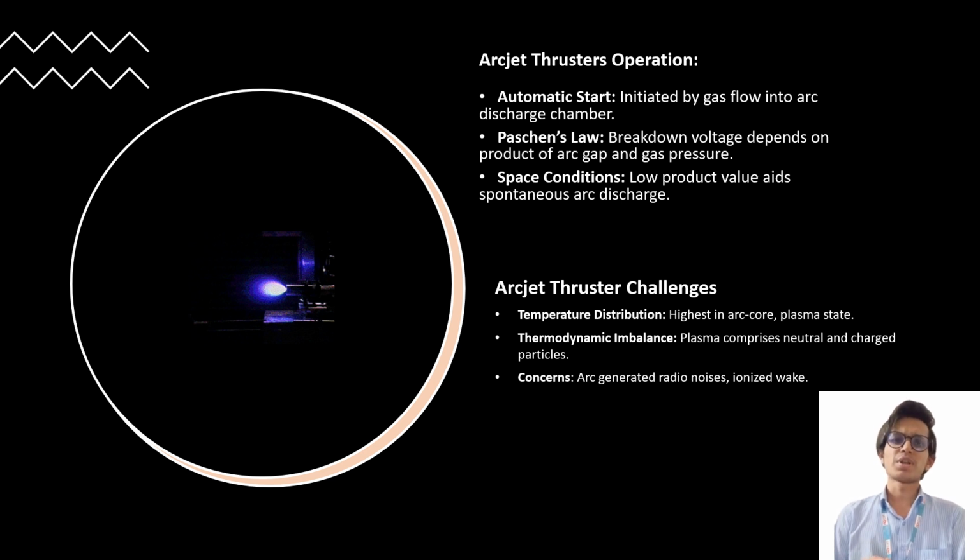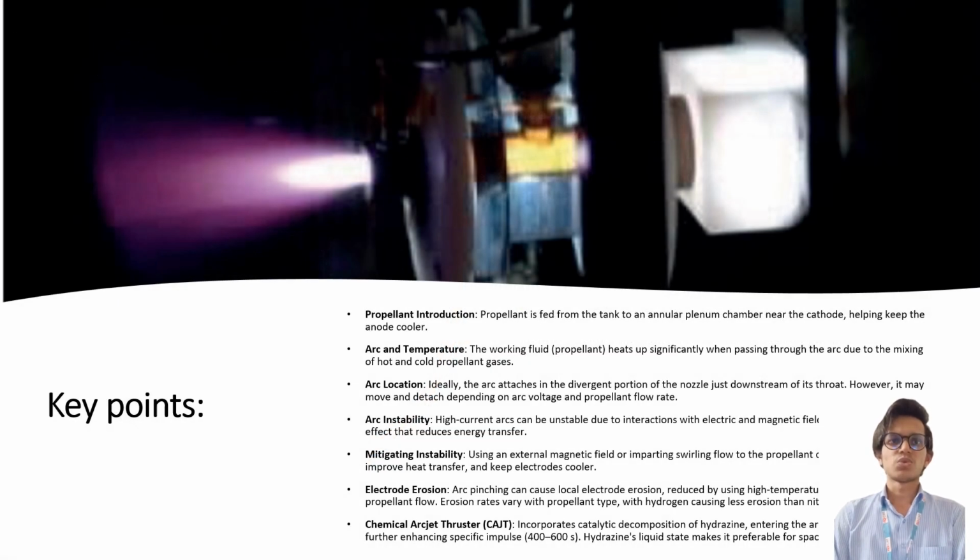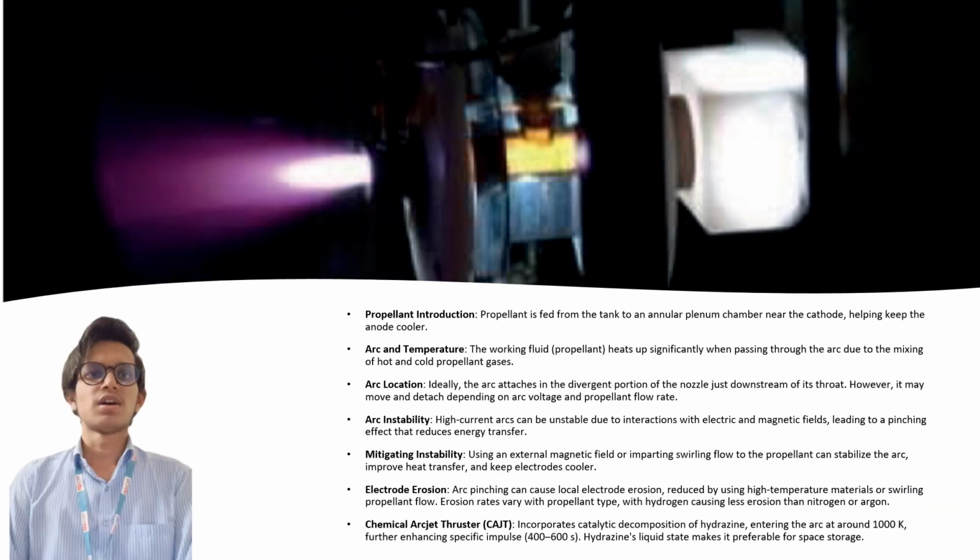Challenges include temperature distribution, thermodynamic imbalance, arc generated radio noises, and ionized wake. However, these challenges are met with innovative solutions to ensure the stable and efficient operation. So, key points and challenges. Propellant introduction is crucial with propellant feed near the cathode to keep the anode cooler.